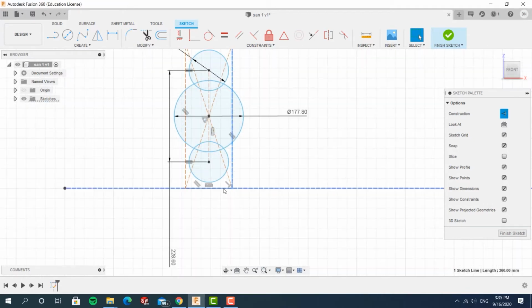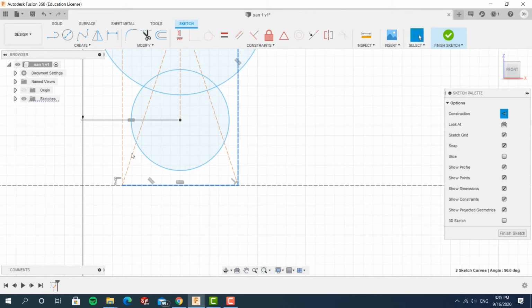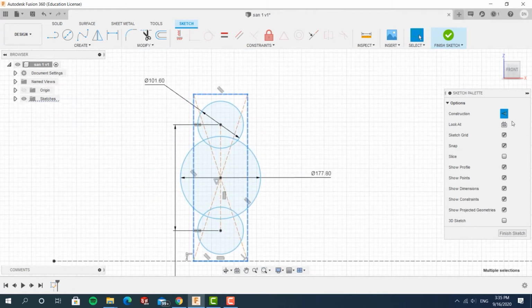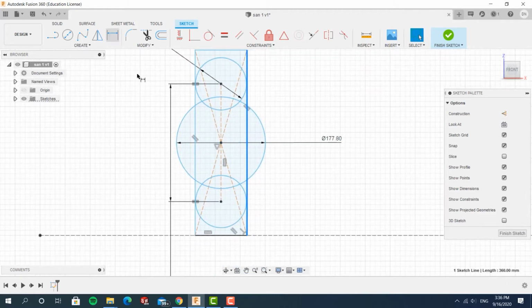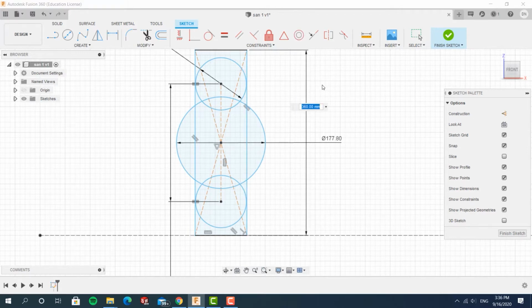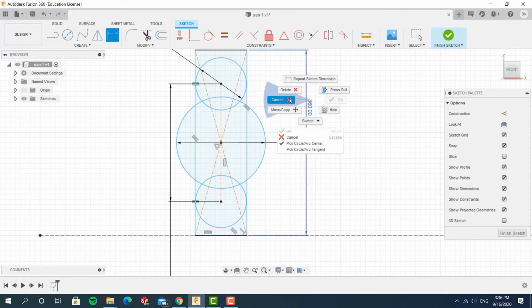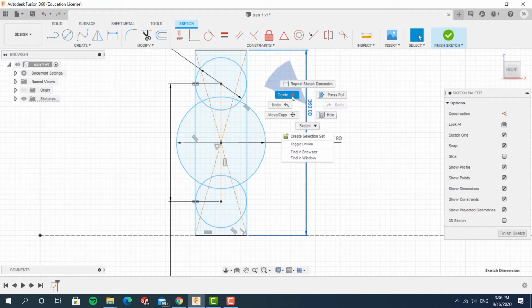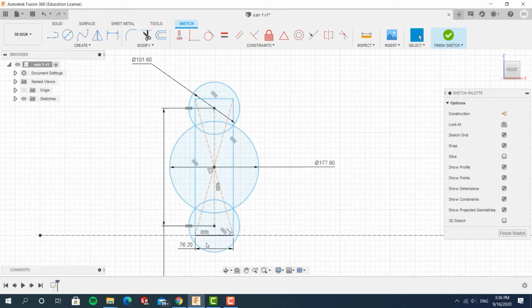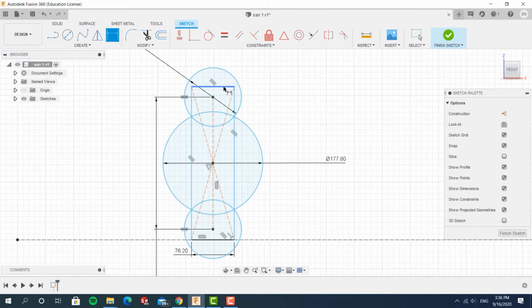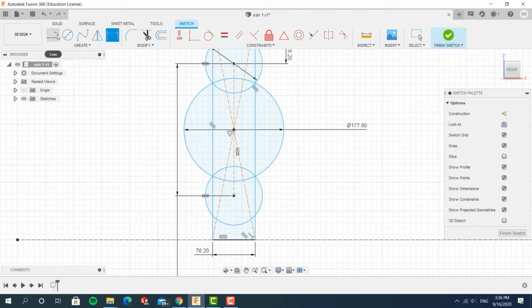So basically, I'm drawing out some slots so that the motors and the wheel can slide in and out a bit. And that also needs a whole lot of sketching. So as you can see here, I just draw the basic numbers like the thickness of the aluminum, the wheels that I'm going to use, the size of the ball. Then I can start to figure out all the other numbers. Basically, the motor is going to be on an aluminum piece, a small piece only, and that piece will slide along a frame that is going to be the actual shooter.